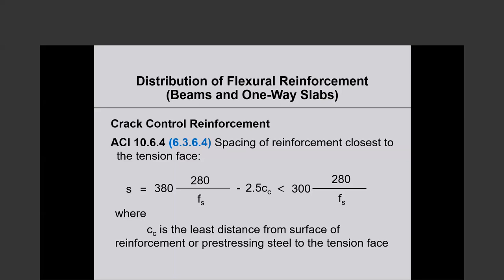Okay, so spacing of reinforcement closest to the tension face s shall not exceed the value given by the expression that you see, 380 times 280 over f sub s, where f sub s is the stress in the tension reinforcement under service level loads, and we will talk about that, minus 2.5 times clear cover.